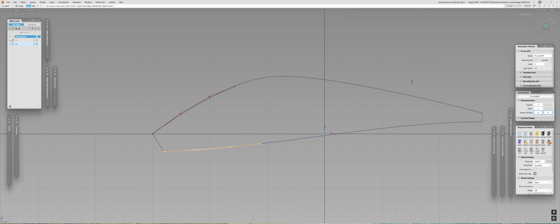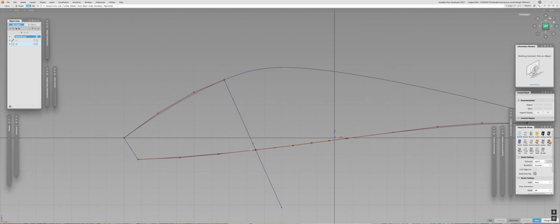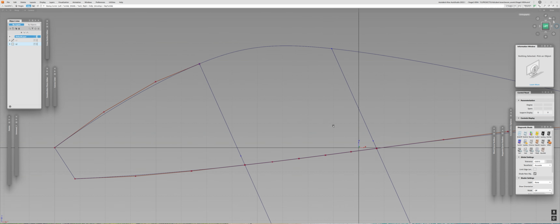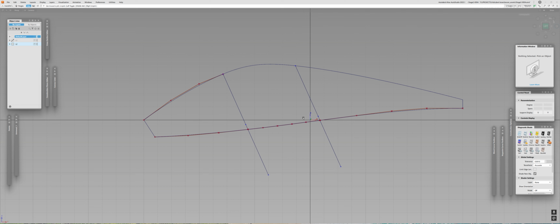Didn't I miss anything? Oh yeah, one important thing about the cut. So I said that there are specific parts where I cut this, and I did it using the tool called line perpendicular. It's in the key point curve toolbox. So here is how it's done. Here, as you can see, where the intersection is, the line has been separated. Same here. Now, why did I do this? Why did I do it specifically this way? Why didn't I really guess? Well, I wanted to have one of the angles perpendicular.